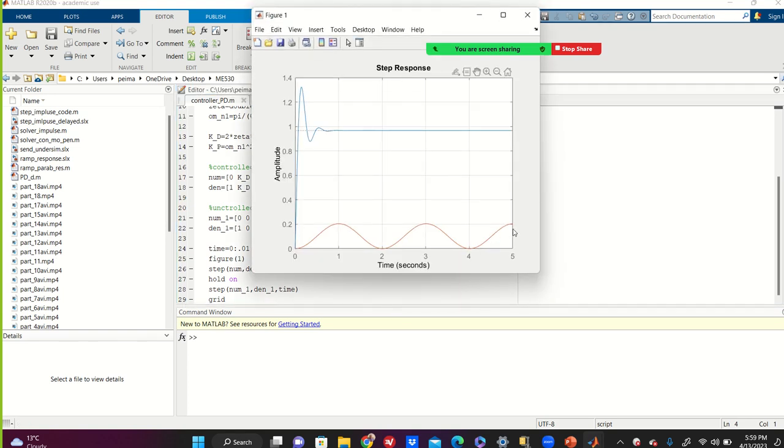With this, the oscillatory response is stable, with almost 0.2 peak time and 25% what? Overshoot. Almost 25% overshoot. Here is almost 25%. And the peak time is that. Okay? Understand everyone? Yes? Yes, everyone? Okay, so you see that now design your first controller.